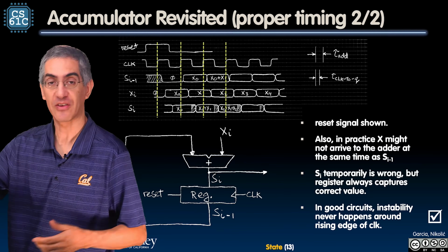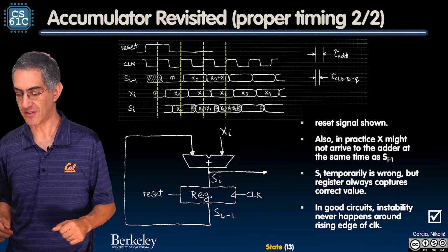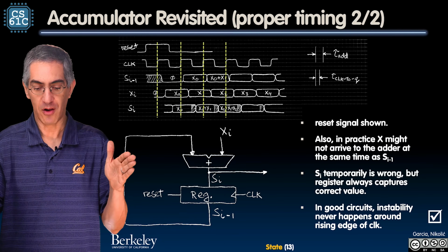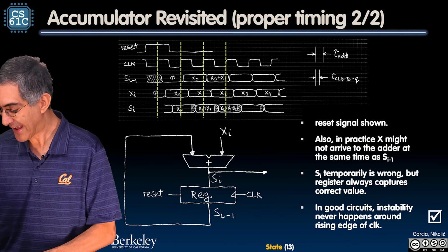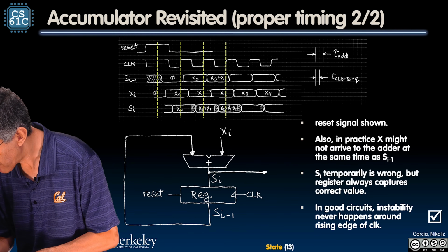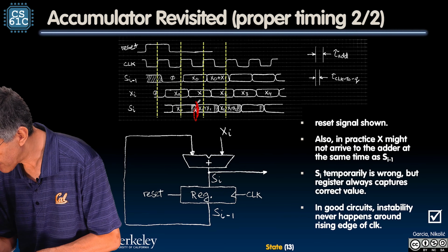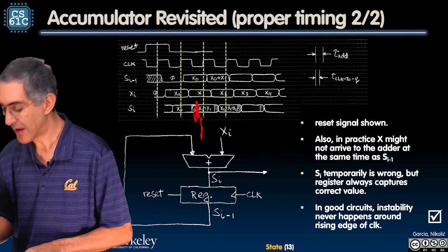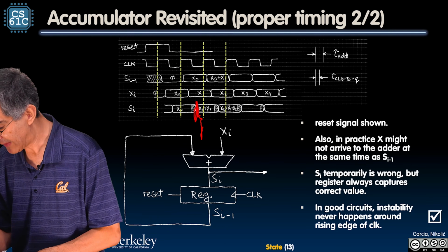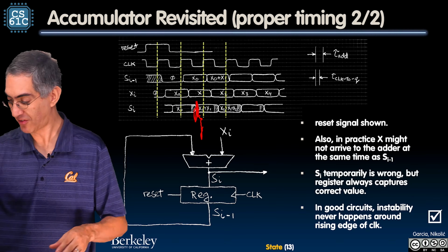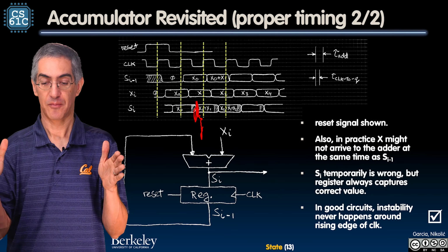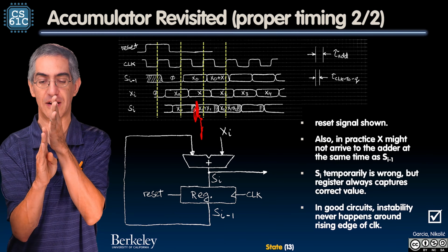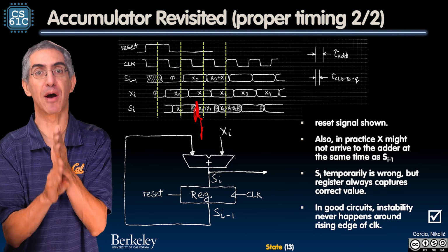This is going to work perfectly as long as I have a nice slow clock frequency, a big old long period. This starts to fail when the delay where it's stable, right here, S of I is stable. But what if this is the line for T setup, and it's a little wiggly? Well, it's still good. It's stable before T setup. And as I'm making the clock period smaller and smaller, now T setup is getting closer and closer to when it is stable. And when it just crosses that, that's my problem point.